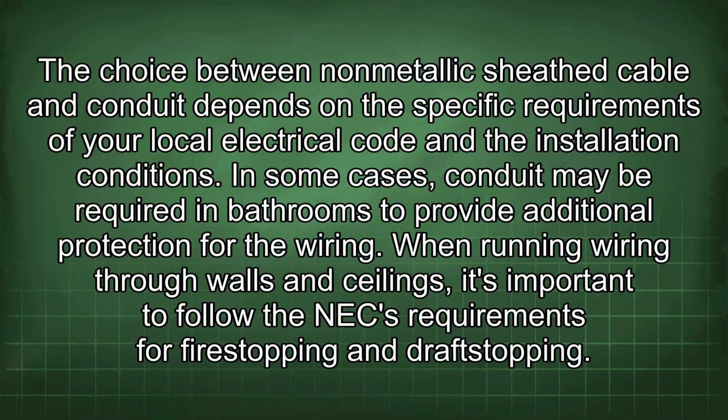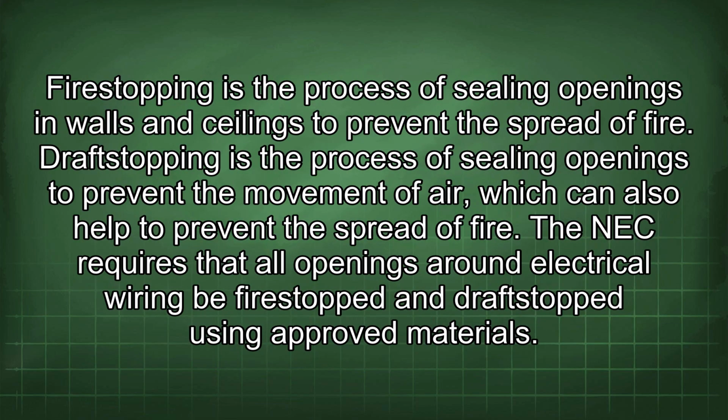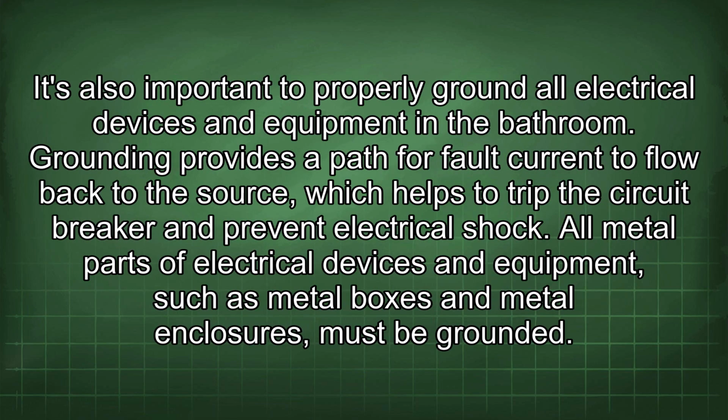When running wiring through walls and ceilings, it's important to follow the NEC requirements for fire stopping and draft stopping. Fire stopping is the process of sealing openings in walls and ceilings to prevent the spread of fire. Draft stopping is the process of sealing openings to prevent the movement of air, which can also help to prevent the spread of fire. The NEC requires that all openings around electrical wiring be fire stopped and draft stopped using approved materials. It's also important to properly ground all electrical devices and equipment in the bathroom.